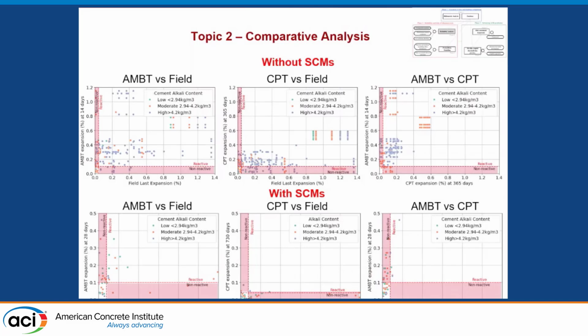And then we have opened up that for mixes without SCMs and mixes with SCMs, knowing that for ourselves in the world and research of alkali-aggregate reaction, whenever we have mixes without SCMs, our intent is to test the reactivity of the aggregates. Whereas whenever we have with SCMs, our intent is to see the performance of that mix, aiming to mitigate the potential reactivity of the aggregate. And you look at those and you see, well, I will have lots of issues in the field, because if you look, some of them are well classified, but most of them are not well classified.